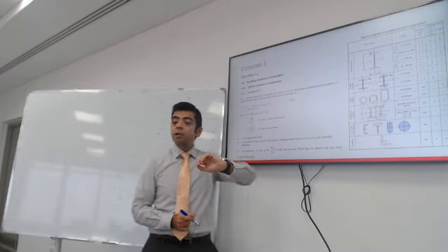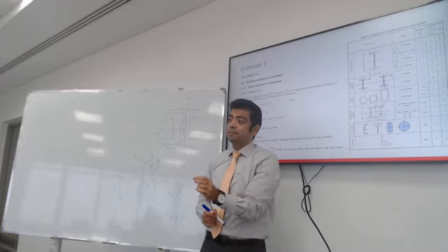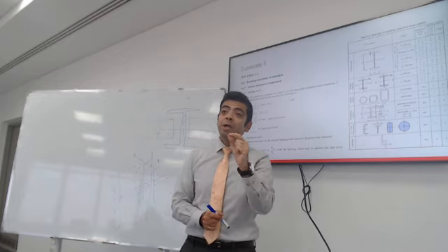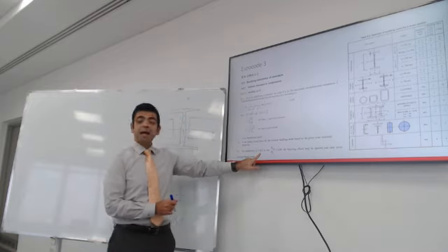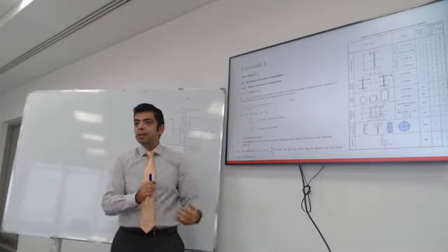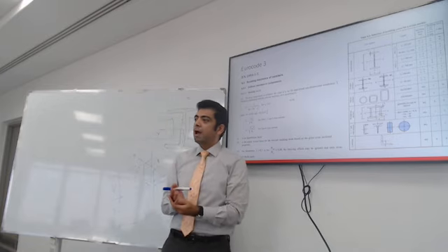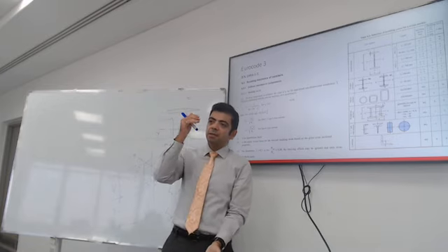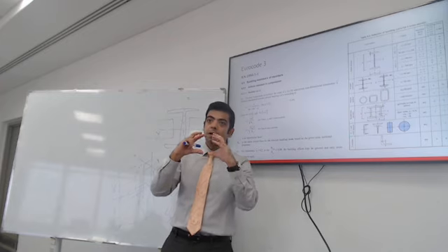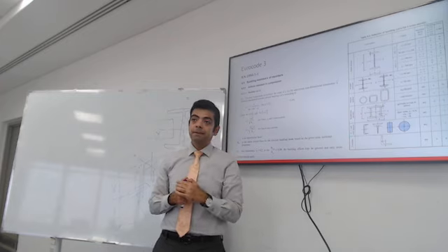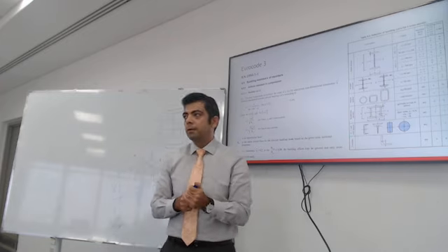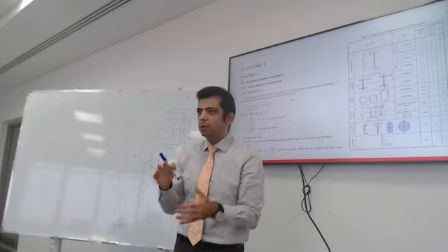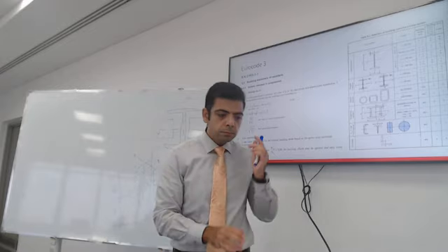I want to share with you a very interesting check. If your slenderness ratio, lambda, is less than 0.2, most probably there is no buckling. You don't have to check for buckling. It's just going to be the axial strength according to the material. Check 1 will govern, which means that your column is very short and very stiff.